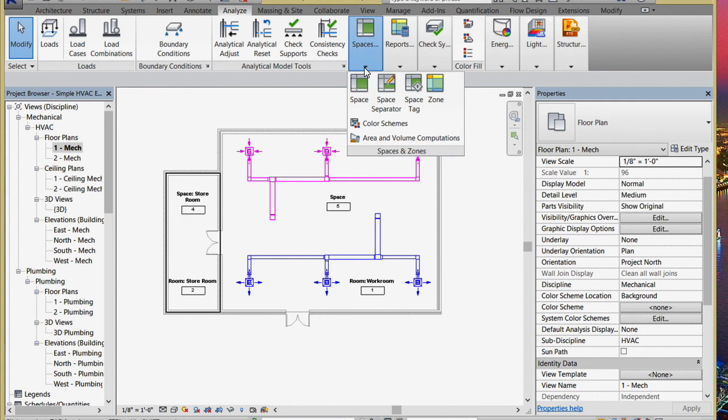Let's talk about zones. Zones are really just collections of spaces that are essentially going to share the same thermostat. They're going to have the same set of thermal controls. So for every zone, we're going to choose what the comfortable cooling set point is and what the heating set point is. Often zones are made up of several spaces put together. They don't have to be.